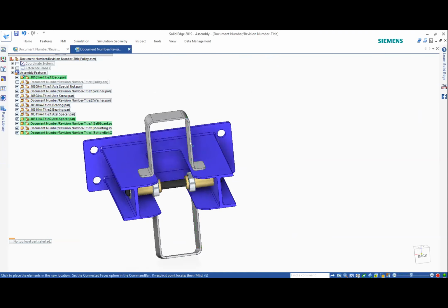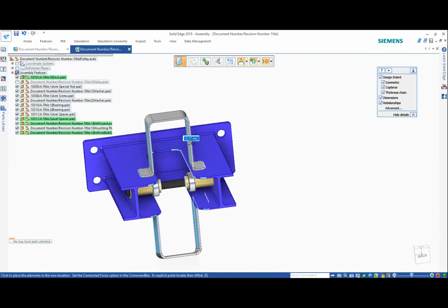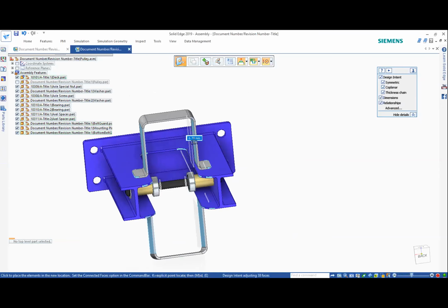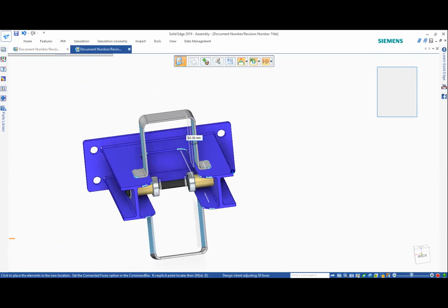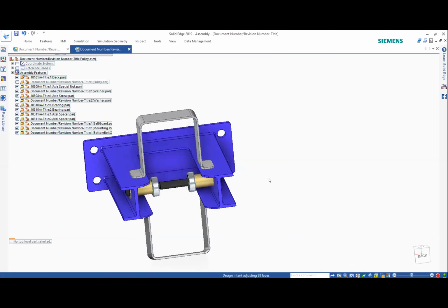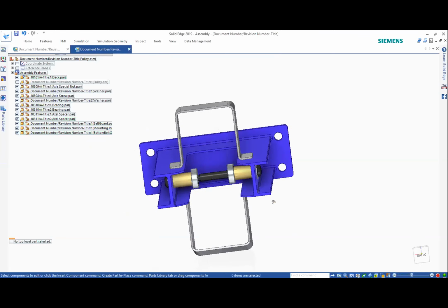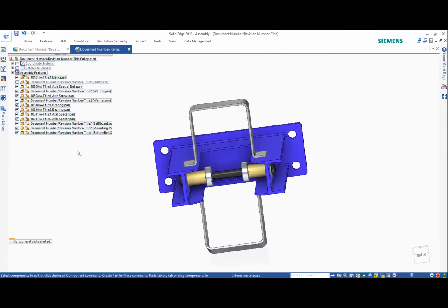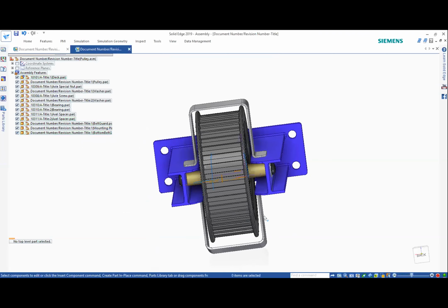And then I can just do this. Press on the arrow again, and just move everything, right? Do 10 again. You guys see I just moved multiple parts at the same time. Yep. This sheet metal, that sheet metal, and you bring the pulley in, there is no interference anymore.